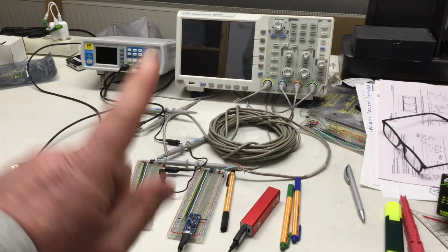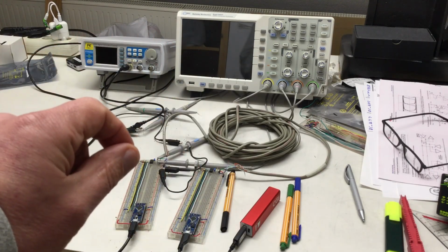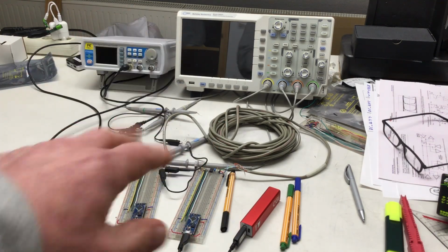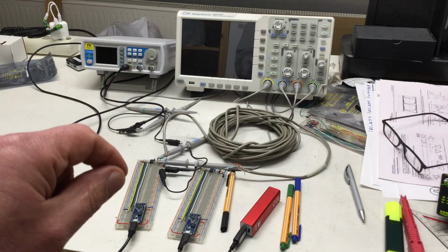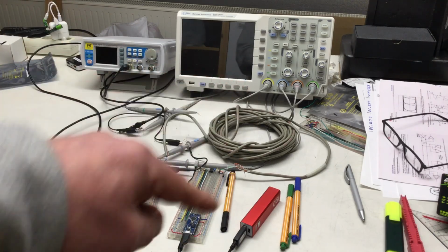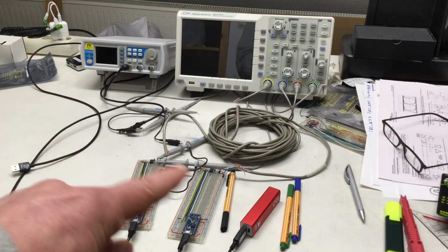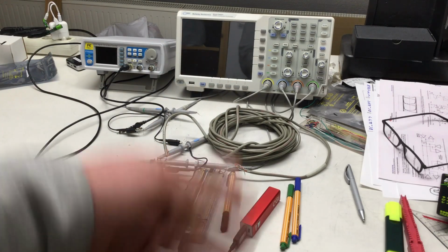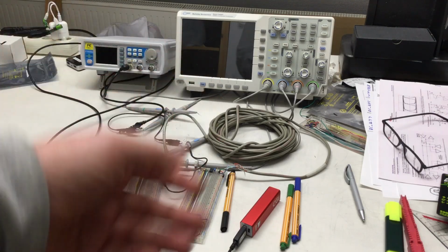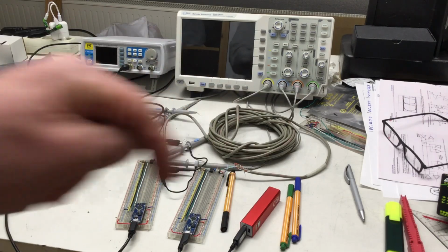Welcome back to the second video about the details of RS-485 communication. In the last video about the basics of RS-485 communication, we established a serial link via 10 meters of Cat3 twisted pair cable between two Arduinos using two SN75176B transceivers. Card here, link in the description.